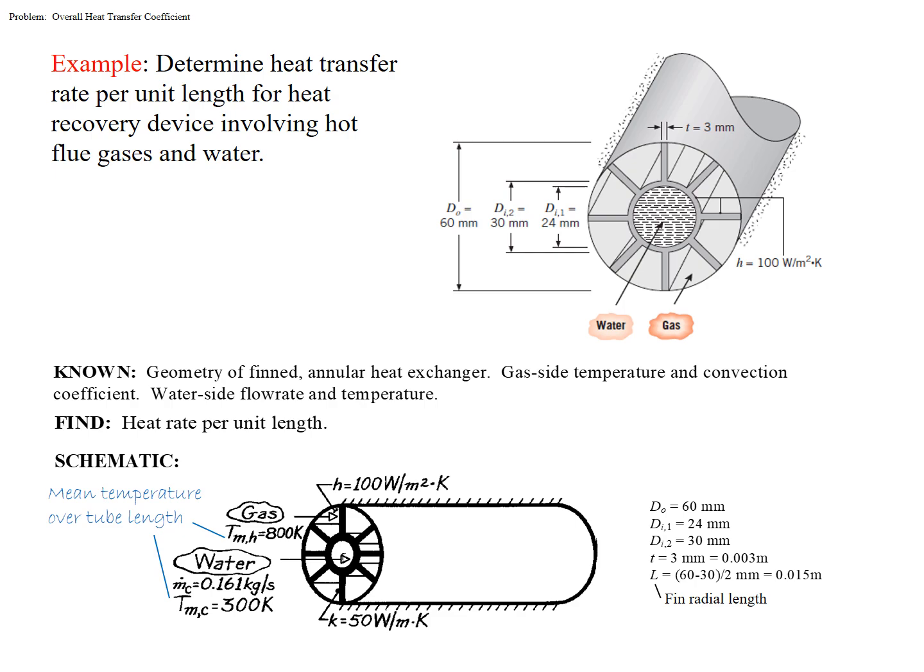Note here that your T values say T_m,h and T_m,c. H is for hot, C is for cold, and m is, if you remember from convection heat transfer relations, the temperature at different points in the cross-section of any flow could be different. When we say T_m, what we mean is the mean temperature in that cross-section. So for example, the inlet cross-section of water has different temperatures, but we're going to say that the mean of all those different temperatures is 300 degrees Kelvin. So don't get confused with that m value there.